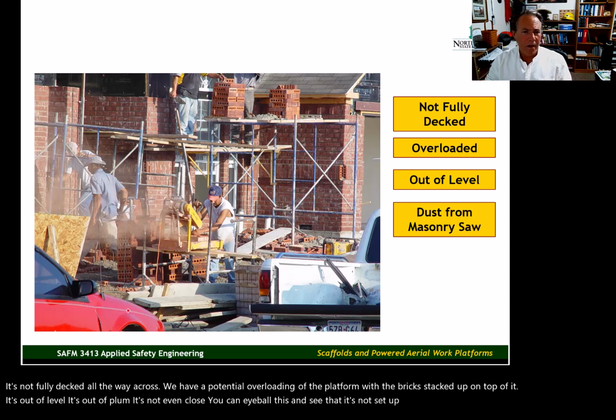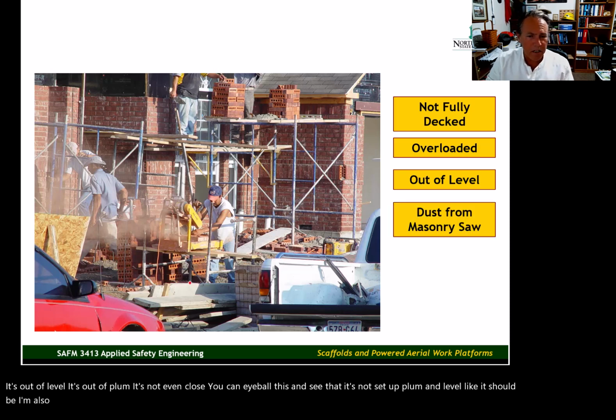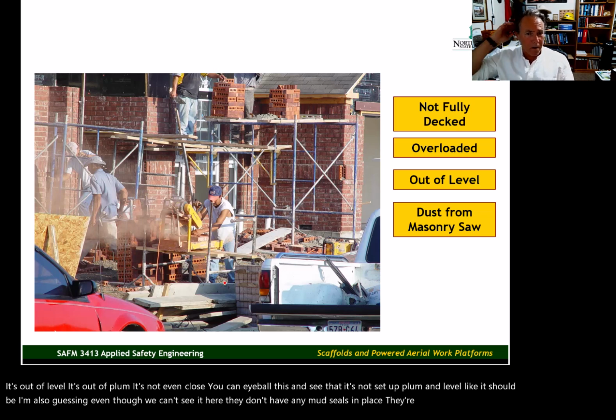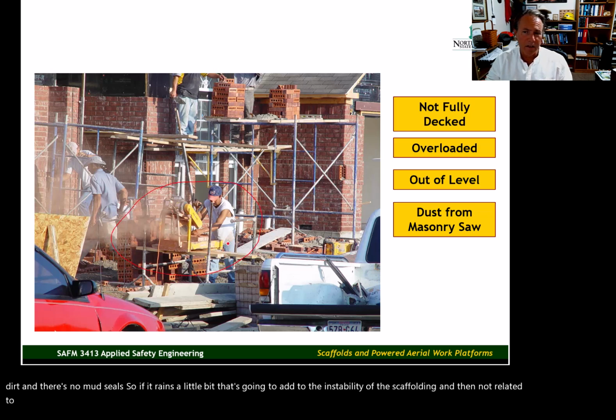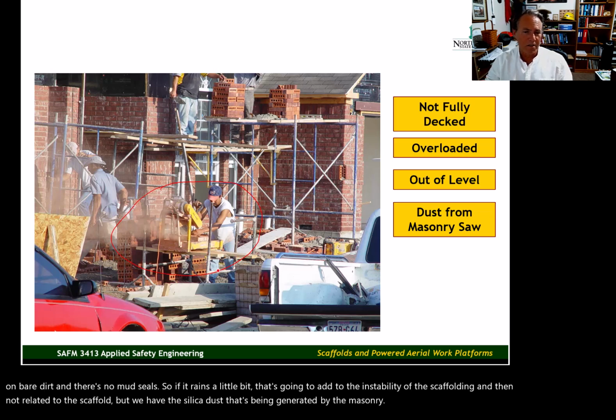It's not even close. You can eyeball this and see that it's not set up plumb and level like it should be. I'm also guessing, even though we can't see it here, they don't have any mud seals in place. They're probably set up on bare dirt, and if it rains a little bit, that's going to add to the instability of the scaffolding. And then, not related to the scaffold, we have the silica dust that's being generated by the masonry saw.